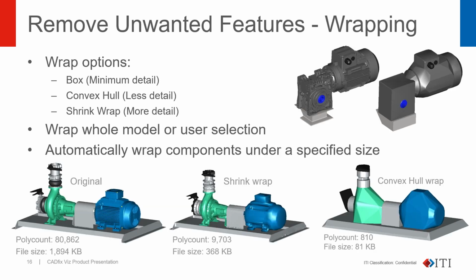This is an example of protrusions. In this case, basically the protrusion is the writing on this part. Holes as well as protrusions can be filtered by shape and by size. So in this case, we have an example of this writing falling under the selection criteria of size, being identified as protrusion and then removed from the part. You can see the reduction and how much simpler the mesh is by doing that.